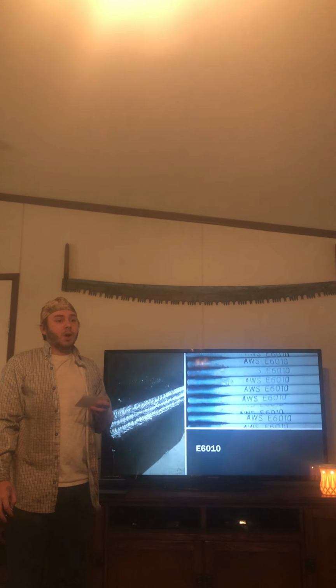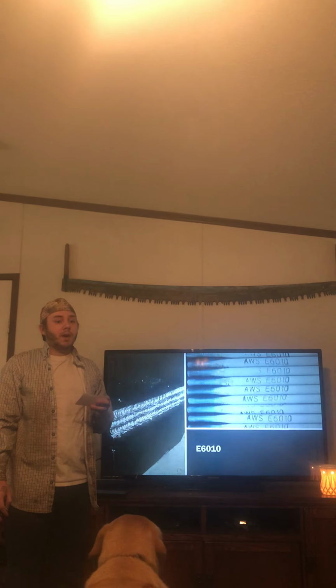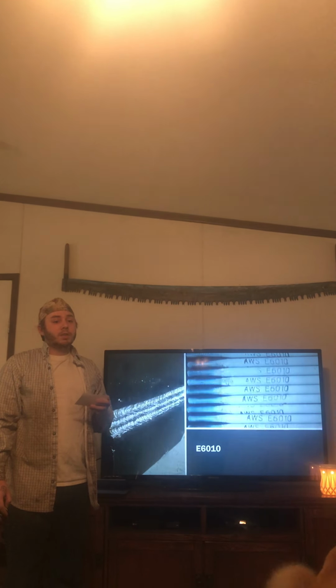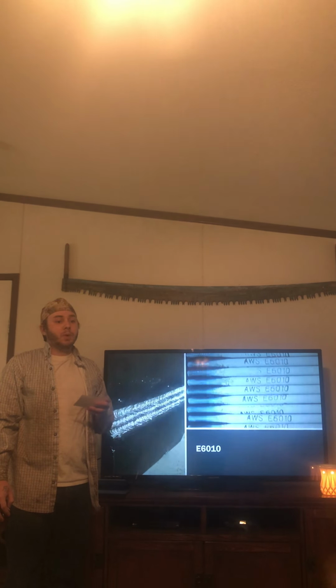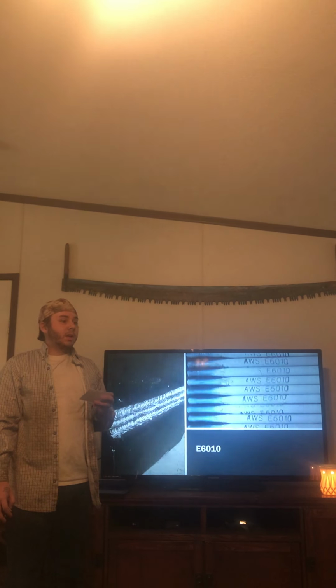E6010 is a mild steel, all-position electrode designed primarily for use on AC power sources. It provides a strong arc force for deep penetration and a fine spray transfer that enhances operator appeal. The fast freezing or rapid solidification of the metal allows welding in the vertical and overhead position. Its light slag eliminates slag holes that are prevalent on some applications with other electrodes. This product can be suited in a wide range of applications. The typical applications include general purpose fabrication, galvanized steelwork, structural work, shipbuilding.